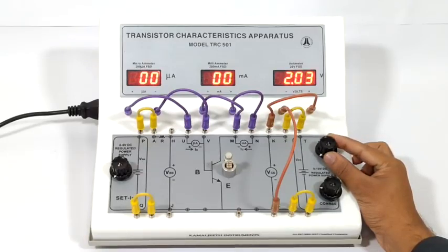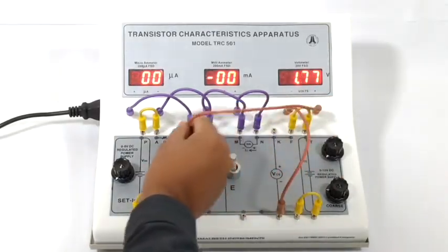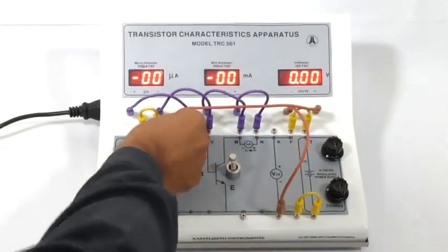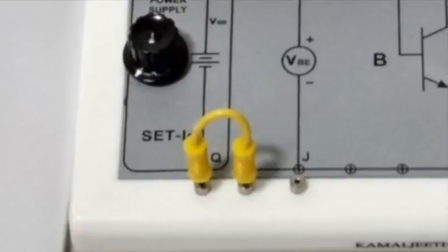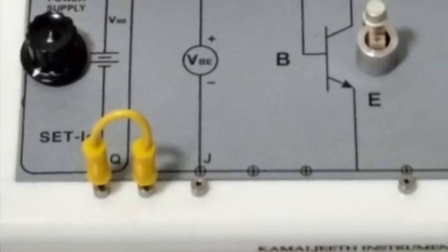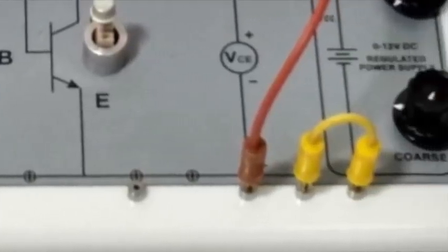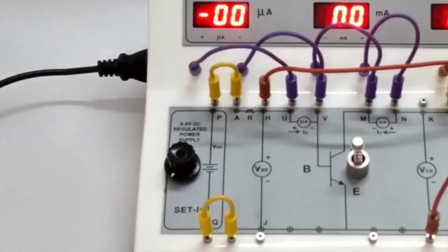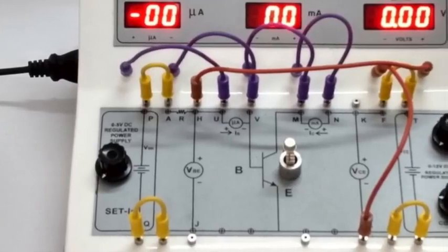Number 6. The positive lead connecting the voltmeter to the circuit in the output side is disconnected at the circuit end, and then connect the same lead to the positive point in the input side. Since all the lower terminals are interconnected in the negative side, no need to change the negative terminal connections. The voltmeter measures VBE. These are the input characteristic connections.